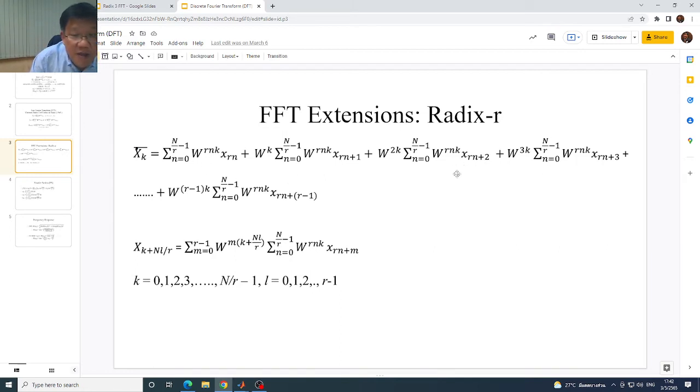Once you get this, now you're ready to use this third formula. You just keep taking the result here, the result you already found, the lattice, this summation over here. Keep storing it as a complex number: the real part kept in one file, the imaginary part kept in the other file. If we retrieve them one at a time and perform this formula, you're going to get the result of the frequency domain of Radix-r here.